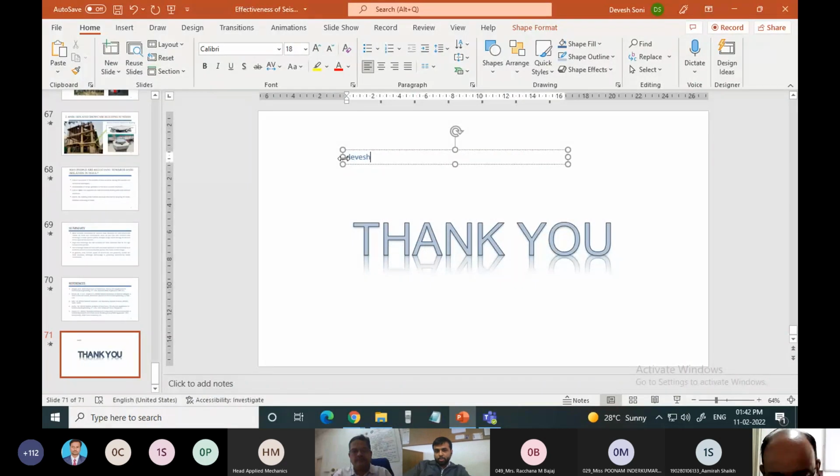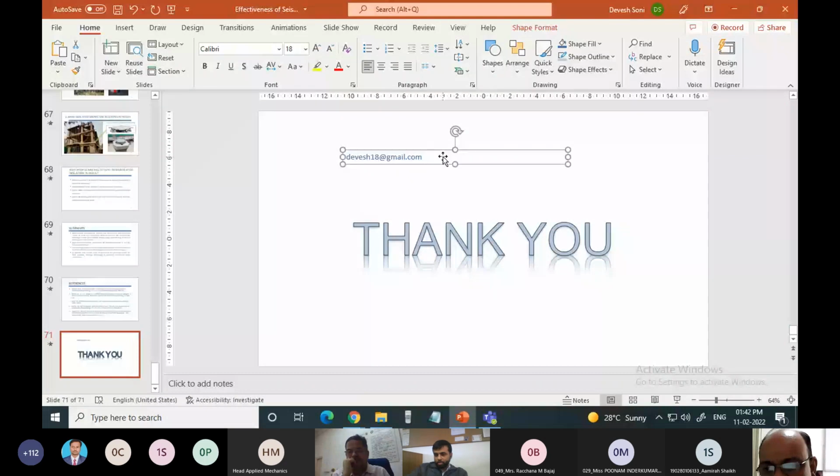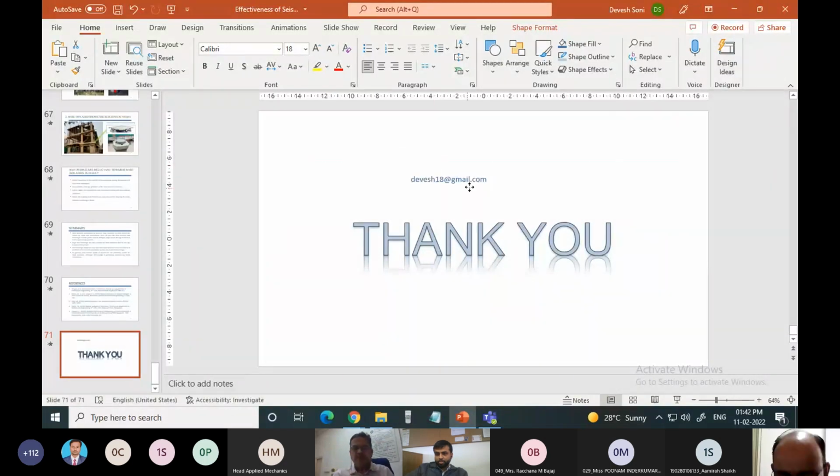I have one question about the response spectra that you showed for the soft soil and medium soil. Sir, is it necessary to have a site-specific response spectra? Because recently I have seen one or two articles saying that the response spectra for the soft soil and medium soil for the Gujarat region is not matching the IS spectra. They have a quite significant difference.